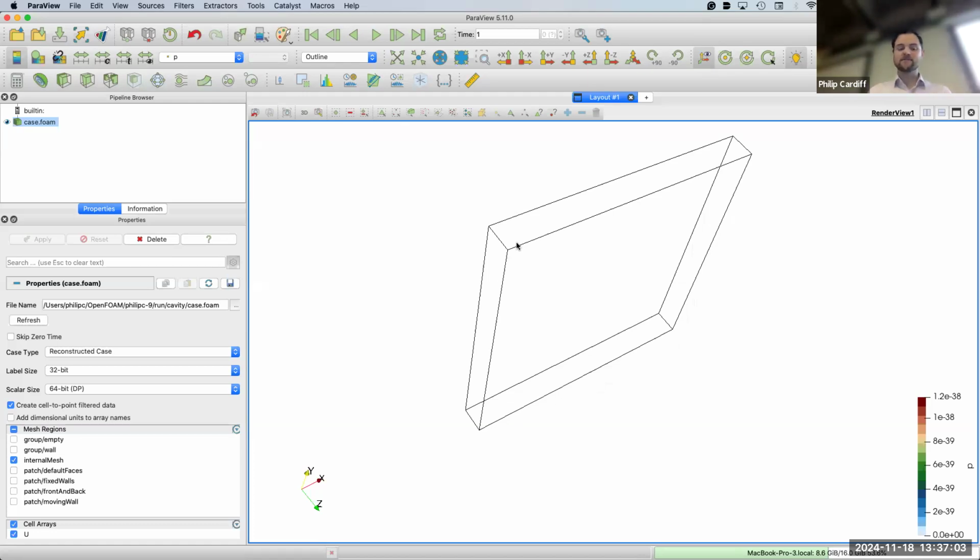So we want to define that quadrilateral region as one patch. So we need 4 vertices. And once again, it's not uniquely defined by 4 vertices. You have to give them in an order, and there's a convention about the order. When we do the right-hand rule again, this time our thumb has to be pointing out for the boundary. So keep on your toes: for the block, it's in, and for the boundary wall, it has to be out. So if we have 2, 3, 6, 7, and I started at 7, it'd be 7, 6, 2, 3. Right-hand rule with my thumb pointing out. So I could start 7, 6, 2, 3, or I could go 6, 2, 3, 7, or 2, 3, 7, 6. And they're all valid definitions.